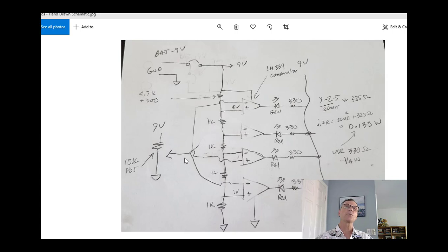And that's why I'm feeding my input, at least for the ones that I drew correctly, into the negative terminal. If that makes you uncomfortable, stop the video, especially if you're going to use an LM339 or a 393, which is just two of them in one package, in your design. Make sure you're comfortable with that logic, because I see a lot of mistakes with that.